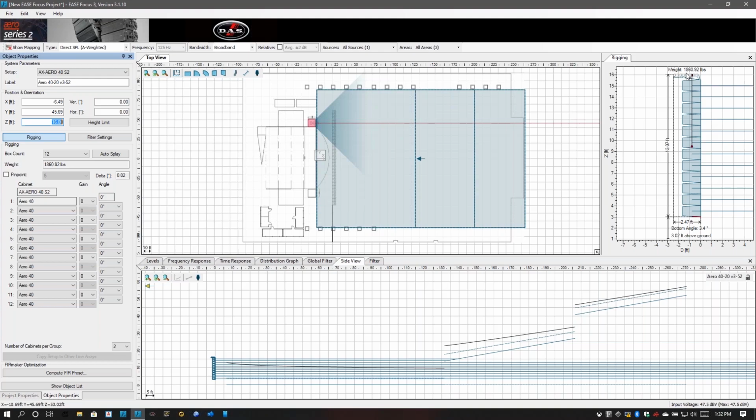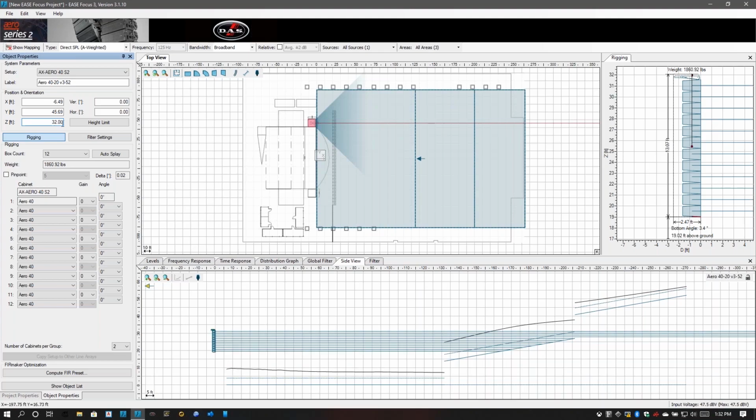So as an example, if we only have 35 feet of height, we are already going to lose at least 2 to 3 feet of that height due to span set, motor, and chain. So if I measure that I have from the ground to the rigging point 35 feet, I might start looking at this PA at roughly 32 feet. Yes, that is probably going to be my max height. I might not stay there, but it's a good starting point for the height that you have, plus the height that we're trying to get for the audience areas.